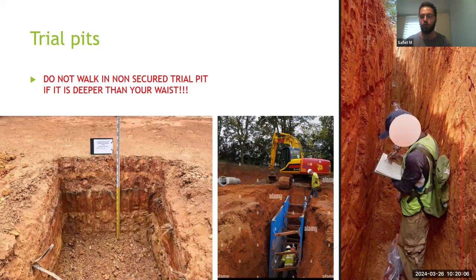People got injured, people got hurt, people got killed on sites. It's really important to be aware of the PPE on site that you need to use, and don't put yourself in danger. No one can make you do it. So in the middle photo, you can see how it actually needs to look. If you're going into a deeper trench or deeper trial pits, you need to support it first, and then you can inspect just the walls of the pit.